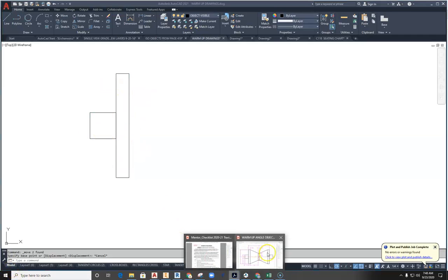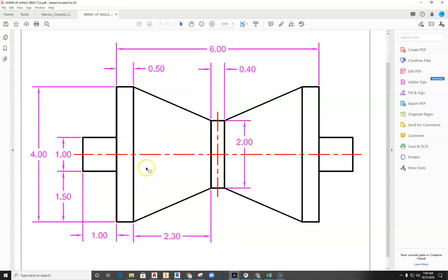All right, so we have our two rectangles set up. Now this is where things generally start getting crazy and befuddling for folks, because we're looking at, well, how do I deal with this? I don't have an angle. I don't have a length of this, but we do have a linear length. So my recommendation is, this is where you want to start learning how to draw lines, use them, and then lose them. We're going to draw a 2.3-inch line from the midpoint on this rectangle straight out to find the location point for this rectangle.